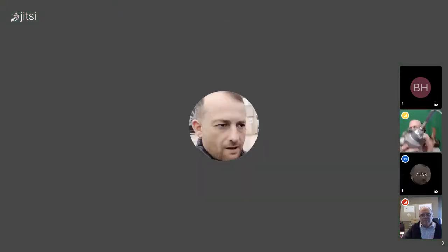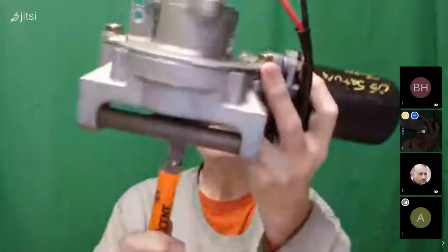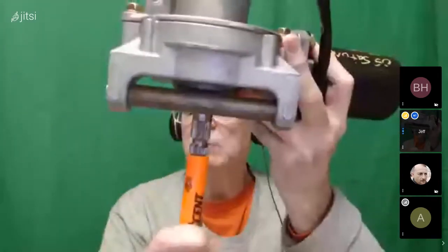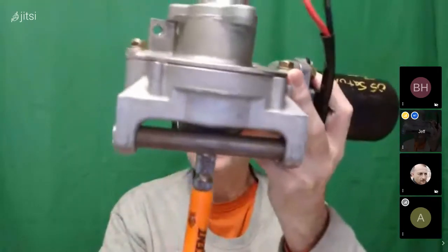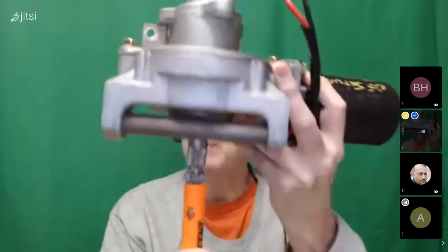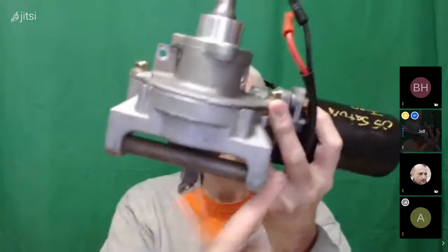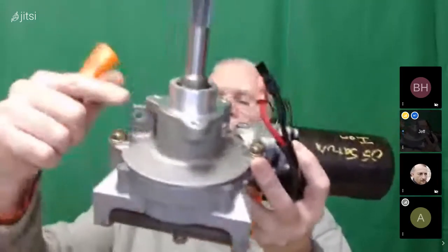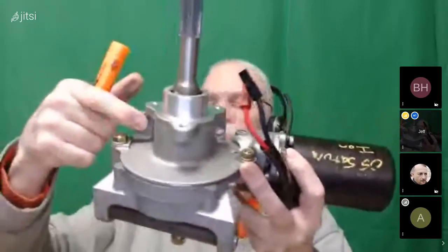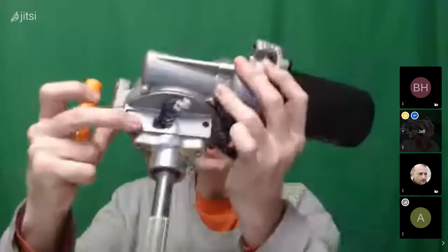Okay, so anyway, we're back to this thing where we've got the motor like this, and here's my steering shaft, and I can lock those together with a piece of pipe. So then I have to figure out some way to keep it, because right now it'd just be hanging in free space. So I have to either put a big bolt through here, or I've got these two small bolts here where the controller is bolted on.